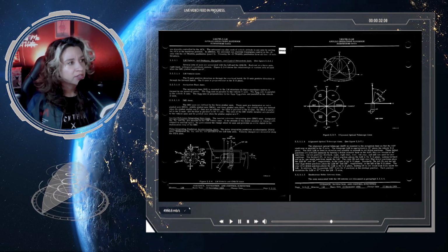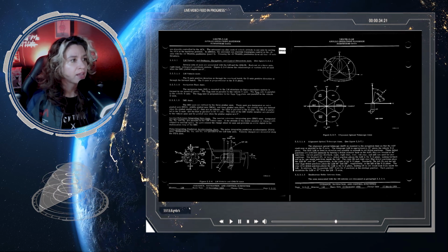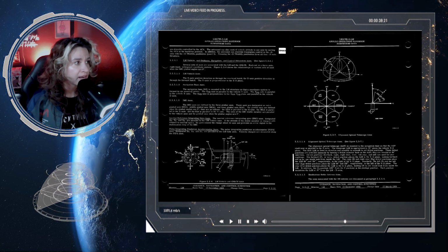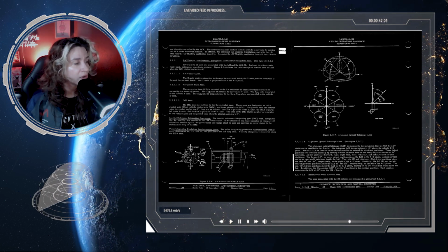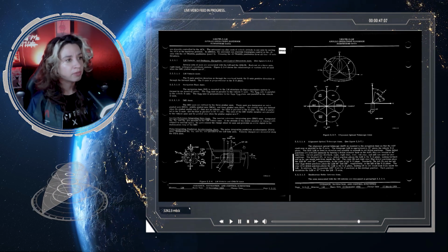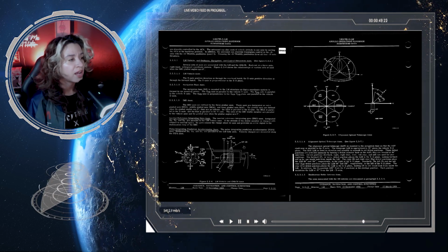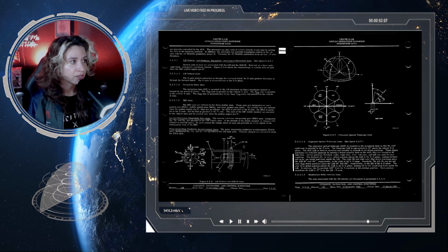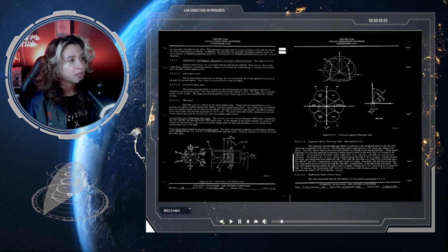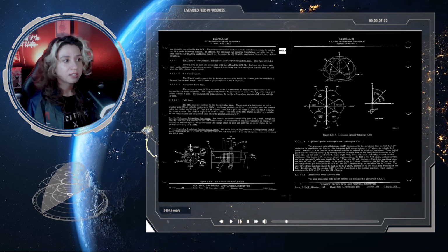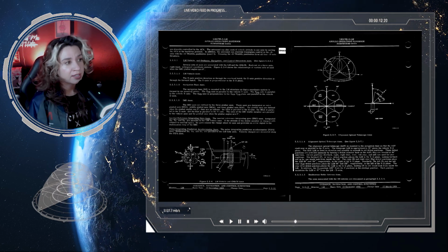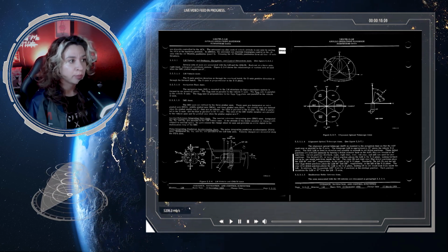Okay, several sets of axes are associated with the LM and the GNCS. Each set is a 3-axis right-hand orthogonal coordinate system. Figure 2.2-6 shows the relationship of various sets of axes when the IMU gimbal angles are 0 degrees. The x-axis positive direction is through the overhead hatch. The z-axis positive direction is through the forward hatch. The y-axis is perpendicular to the xz plane.